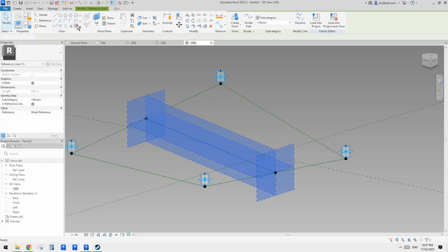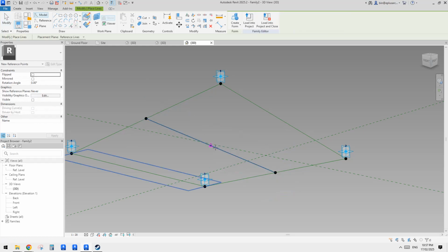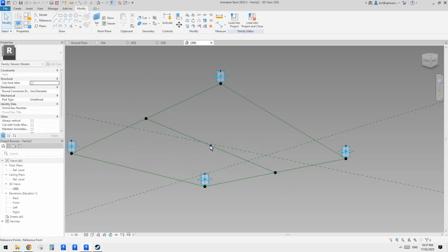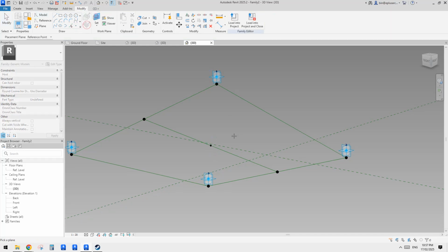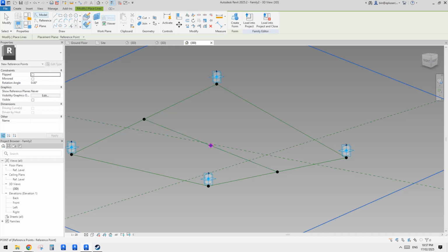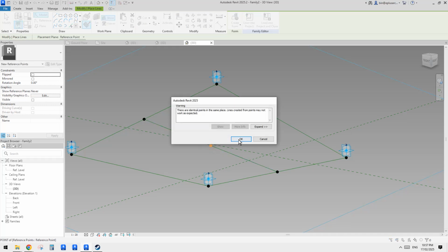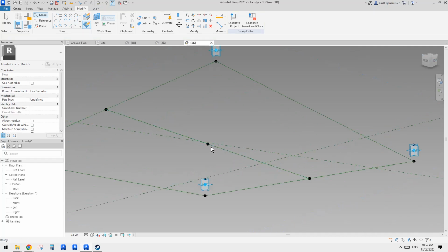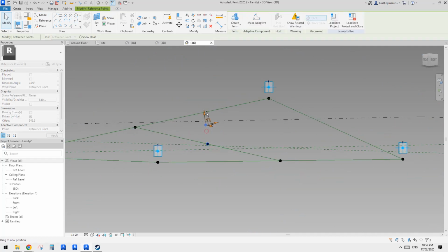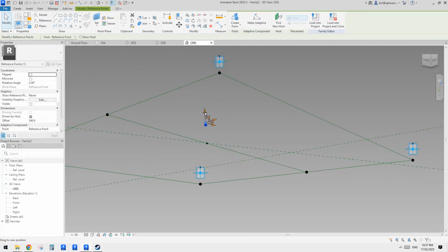And then we can add a point, you draw on face, and the same, do a snap midpoint. From this point, we have the option to place another point onto the work plane. In this case, that's horizontal, or you can just do a vertical as well. It will be fine because we can just offset.